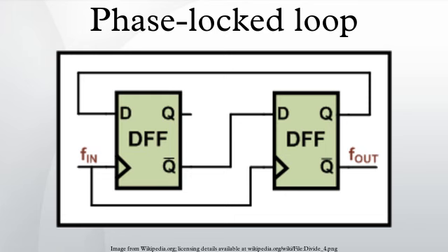When either the reference or signal has a positive edge, the corresponding flip-flop switches high. Once both reference and signal are high, both flip-flops are reset. Which flip-flop is high determines at that instant whether the reference or signal leads the other. The error signal is the difference between these two flip-flop values. The pole-zero filter is implemented by adding the error signal and its derivative to the filtered error signal. This in turn is integrated to find the oscillator frequency.